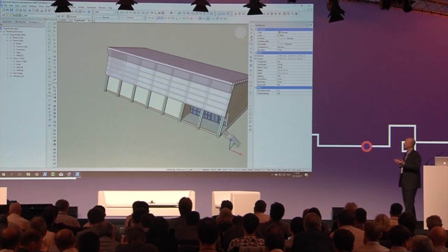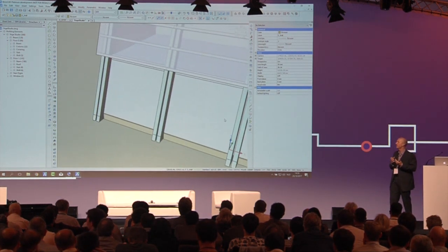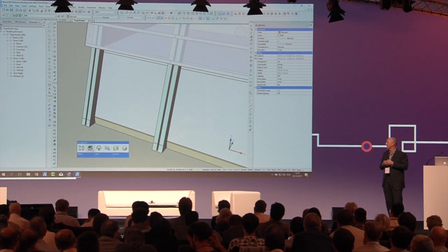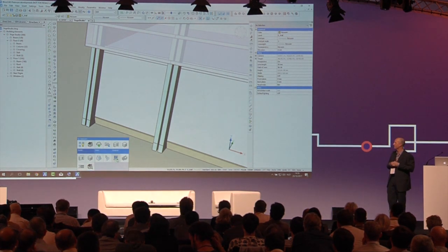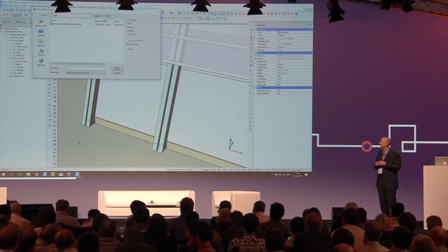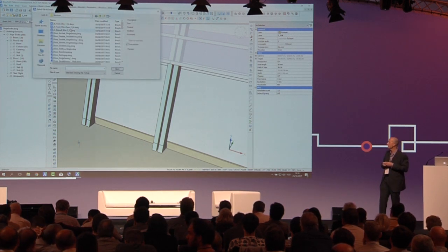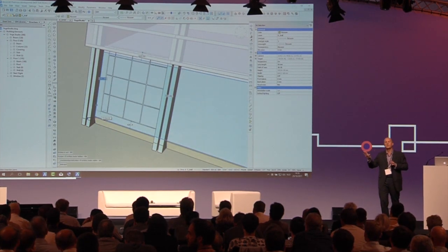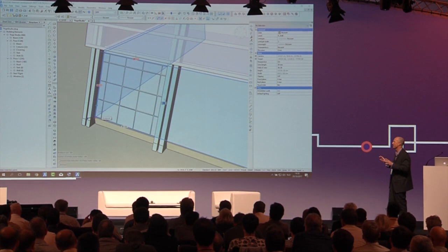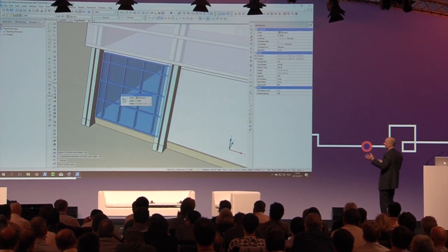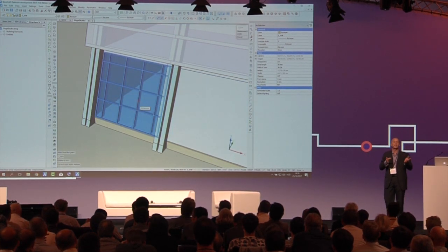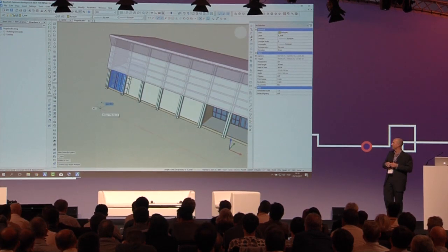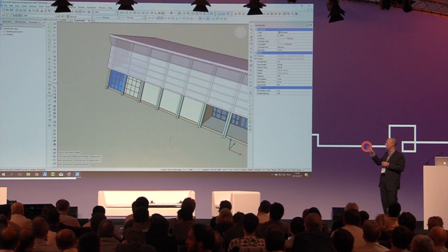Now, let's add some glazing to the facades. So we can do it in the typical way that you've probably done in the past in terms of BIM insert, selecting a window type, and then locating it on the surface that you want, setting the dimensions that you want, and placing it. So we have a glazing assembly here. We can now take that and copy it. And we'll use repeat copy to carry it across the face of those 5 bays.